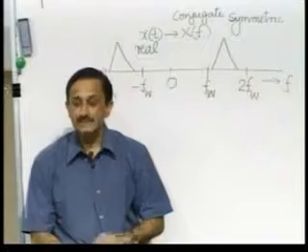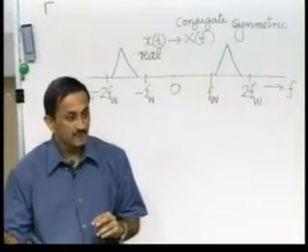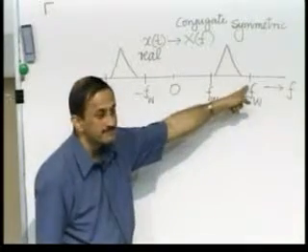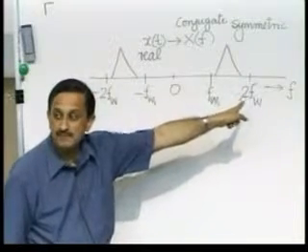Now, if we went blindly by the Nyquist principle, what would be the sampling rate required? 4 times Fw, because the maximum frequency component could be 2 Fw. So, we would expect that you need a sampling rate of 4 Fw.